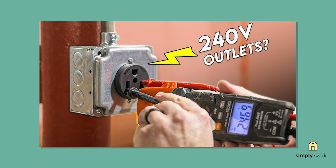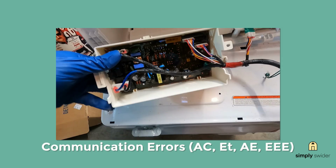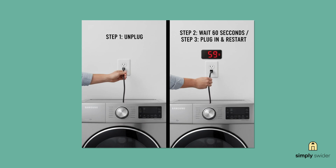Communication errors mean the internal components aren't talking to each other properly. You'll see AC, ET, AE, EEE, or E3 codes when there's a problem with the main control board or user interface. These are the errors that make you think your dryer is having a nervous breakdown. The good news is you can try a simple reset first. Shut off the dryer completely for about 60 seconds, then turn it back on. Sometimes that's all it takes to clear a temporary glitch.